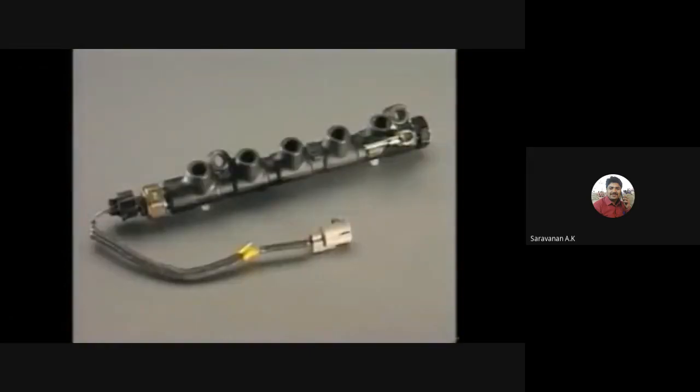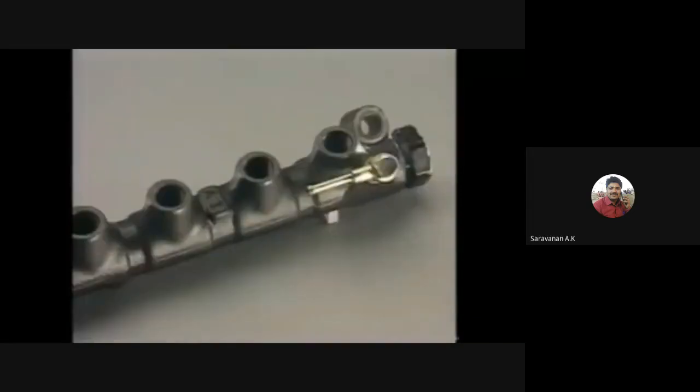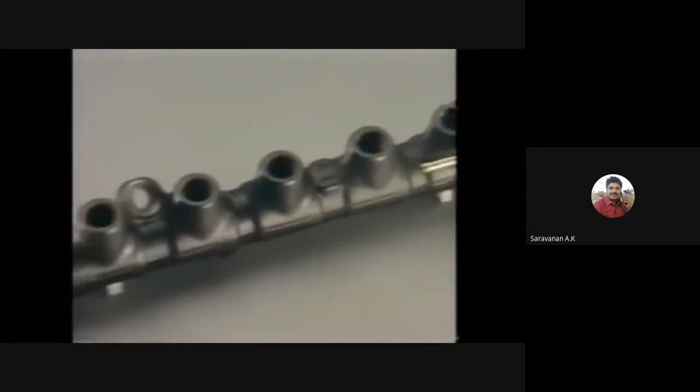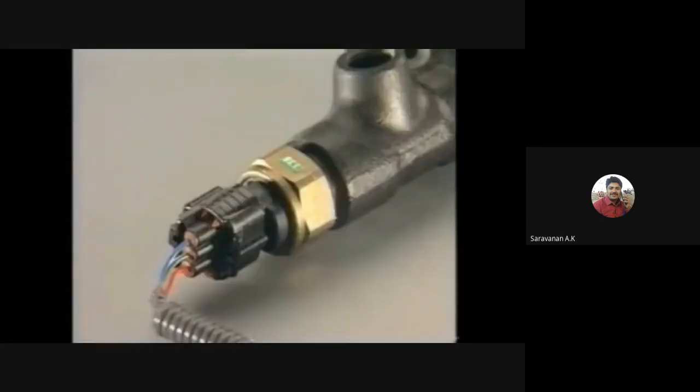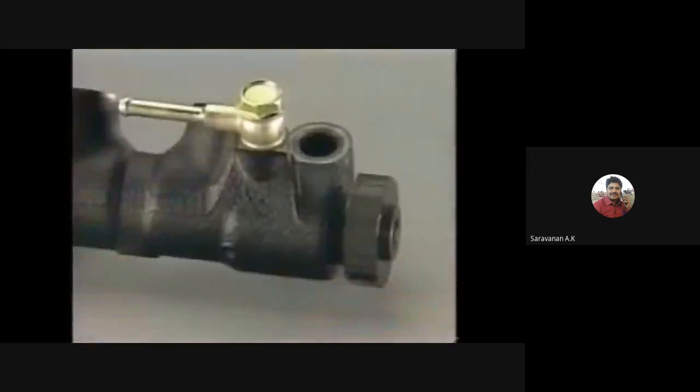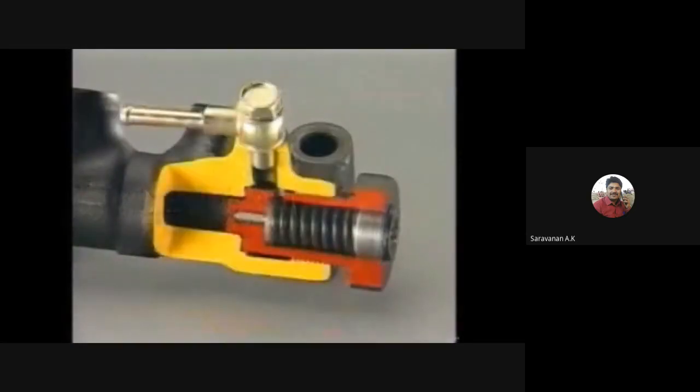The common rail accumulates the fuel that has been highly pressurized by the supply pump and distributes it via the injection pipes to the injectors of the cylinders. A fuel pressure sensor is provided at one end of the common rail to detect the fuel pressure in the rail and to send it as a signal to the ECU. A pressure limiter is provided at the other end, so that in the event of a system malfunction, if the fuel pressure rises abnormally, the pressure is relieved mechanically.